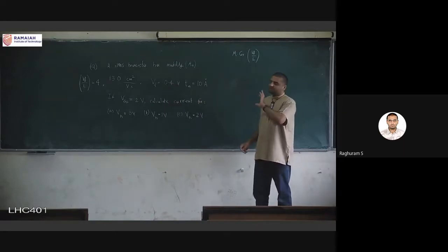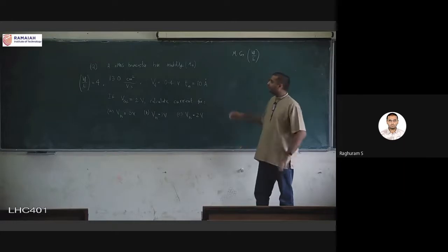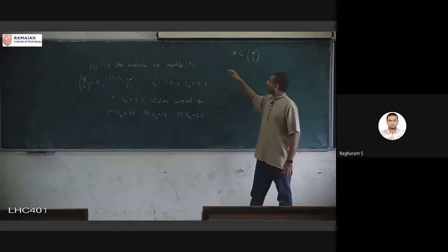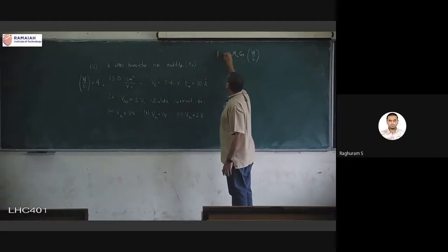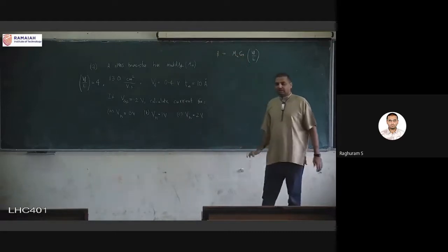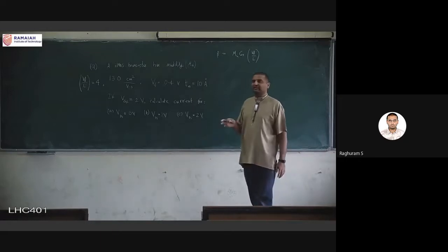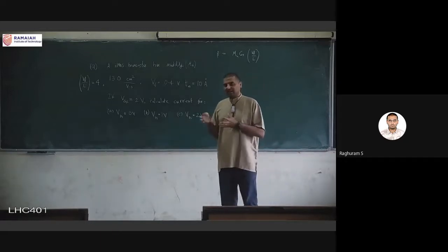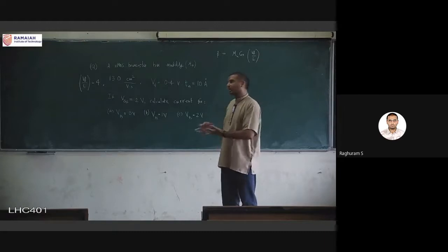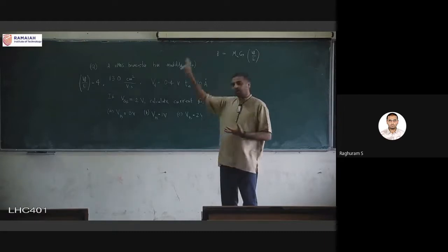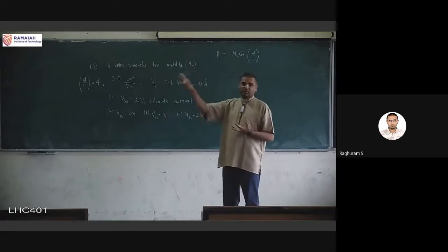Whatever is outside of the current equation part, we will group all those together and call this beta. The advantage of calling this a separate thing is we can calculate this, keep it, and reuse it again and again, because this term is there in all the current equations, both in linear and saturation.